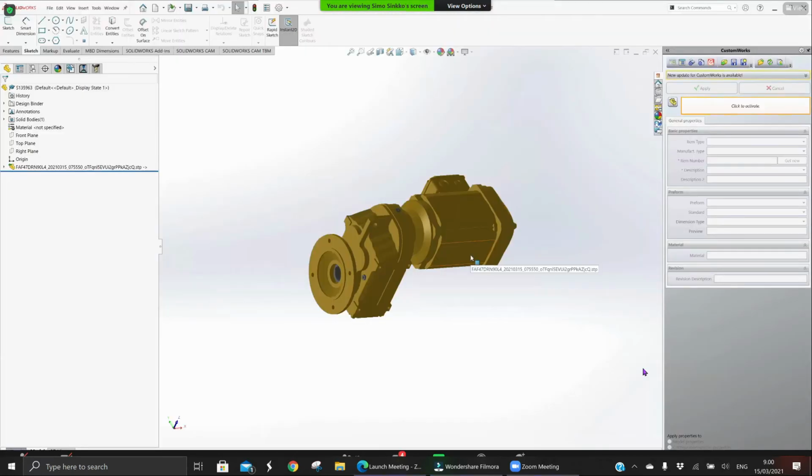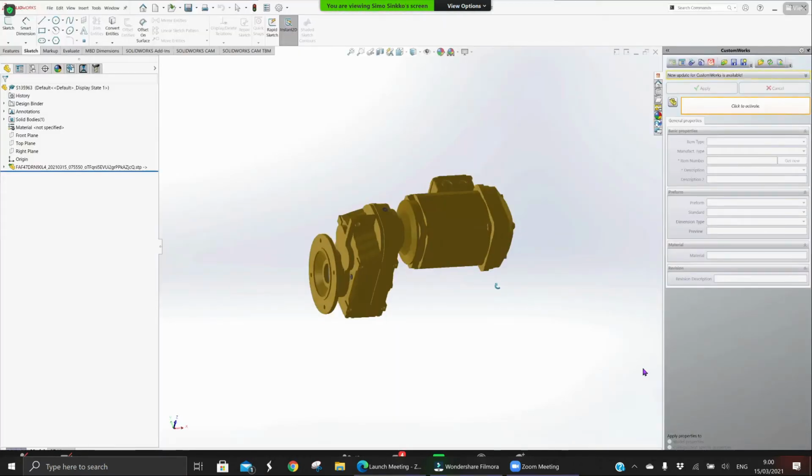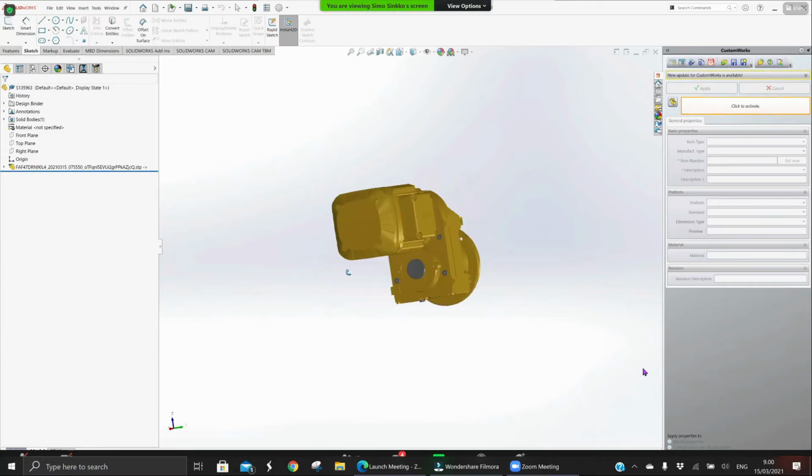So we didn't use any preform, right? Just the description and item number and description. Yeah. I think this preform is not applicable at this point because we don't need to give any raw material for it. It's a purchased component, so the important thing is to give the code that you could use to buy it. If we would like to be more precise, it would actually be important to give the output speed and power options as well. So I gave a little bit too little information.